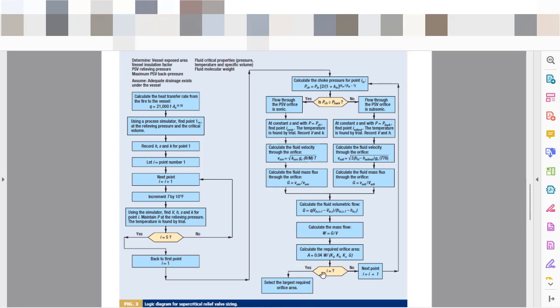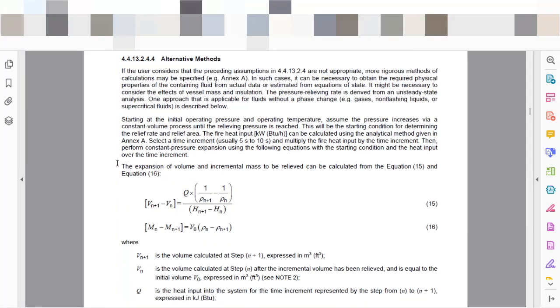So with this, you will have a series of orifice calculations, and you need to verify what is the biggest one. Important to mention that the Aspen Hysys on safety analysis performs the supercritical calculations based on Ryan's procedure, and the API 521 already recognizes this procedure as an alternative procedure that can be used to define the orifice and also the flow calculation.